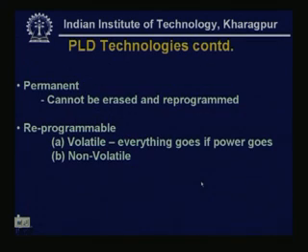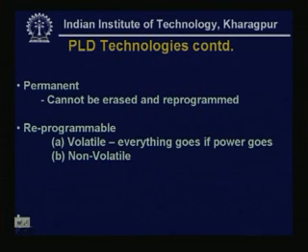Normally PLD technologies can be permanent. Permanent means it cannot be erased and reprogrammed. That means if the memory we use is a ROM, read only memory type, then we have seen that a lookup table can be implemented by memory, and if this memory is a read only memory type, it cannot be changed. It is permanent, cannot be erased and reprogrammed. That means, once we have programmed a design, it is permanent or fixed.